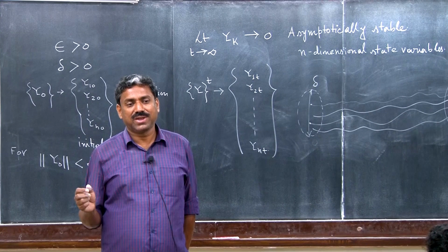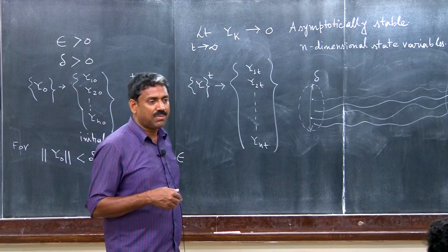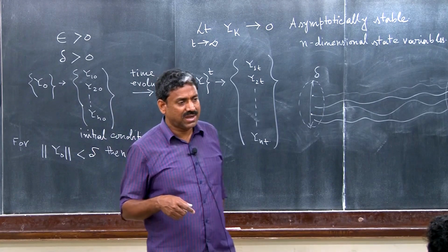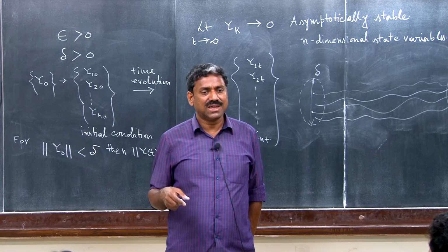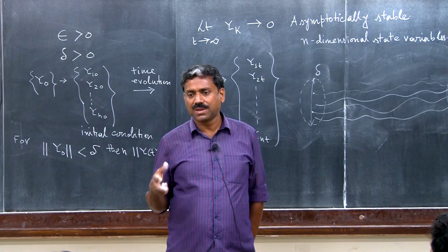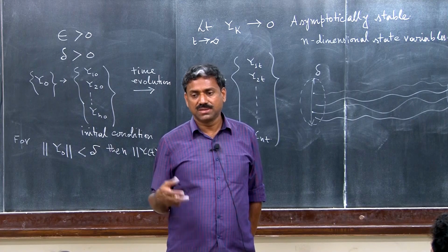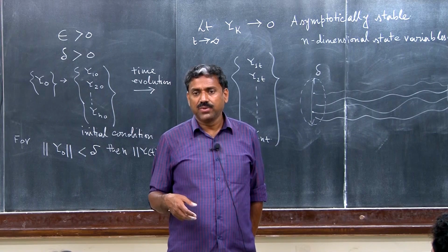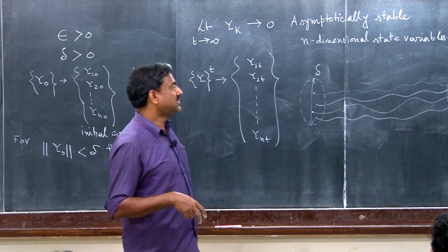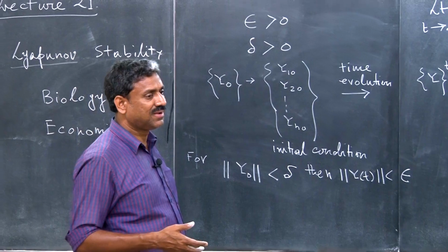So, if you can define it as positive definite, the way we form the Lagrangian for a dynamic system, and from there we derive the equation of motion, right. So, the Lagrangian can sometimes be adopted as a Lyapunov function, you see that. Positive definiteness of the Lyapunov function will also ensure stability, okay.